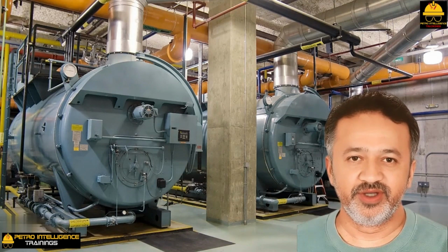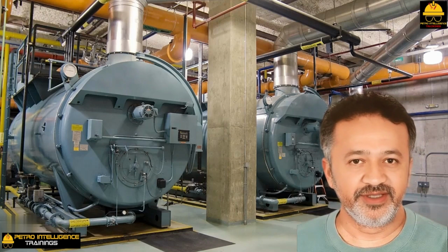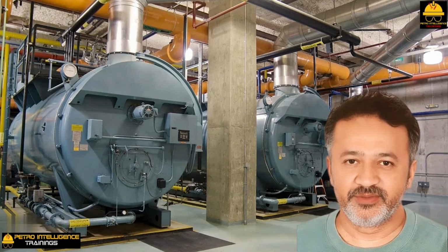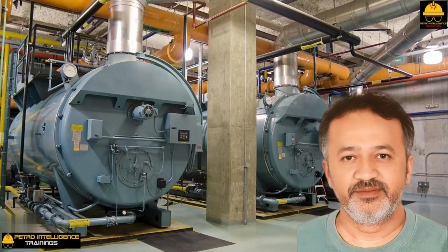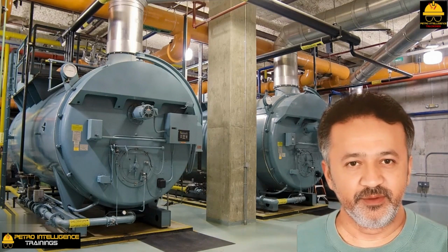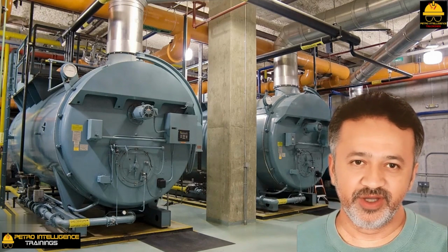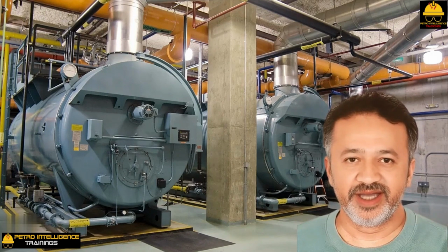Blowdown is the water that is drained out of the boiler to control the accumulations of TDS or silicates in the boiler. Some people drain 10% of the makeup BFW flow. Two types of blowdown from a boiler are used: continuous blowdown from the steam drum and intermittent blowdown from the mud drum. Both will reduce silica. Note that with the continuous blowdown, heat recovery equipment may be economically justified.